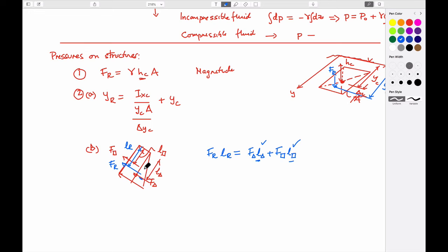You know the forces just by looking at this prismatic distribution. I guess we also know that the resultant force has to be equal to the sum of the triangular and the prismatic distributions, both of which we know, and the only unknown is this magnitude here. So that allows us to define the location that the resultant acts and also its magnitude.